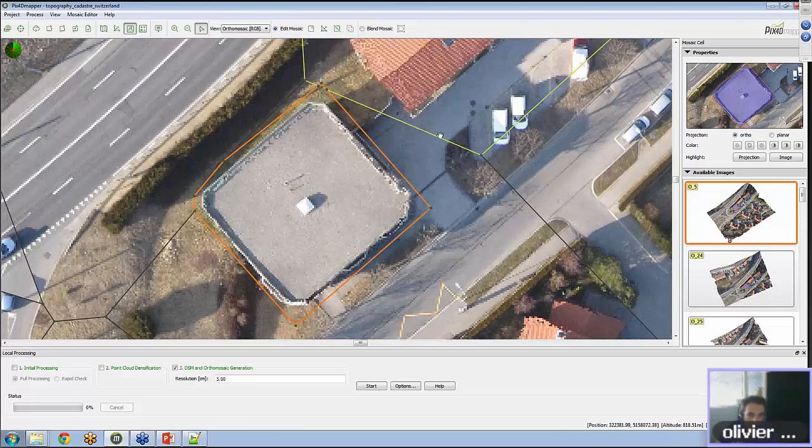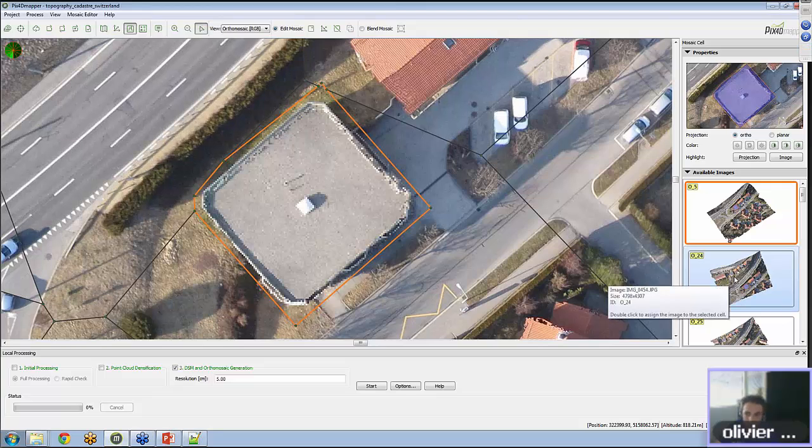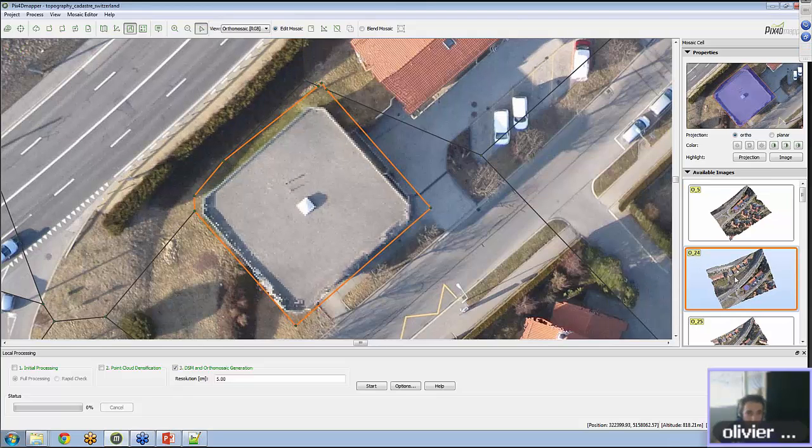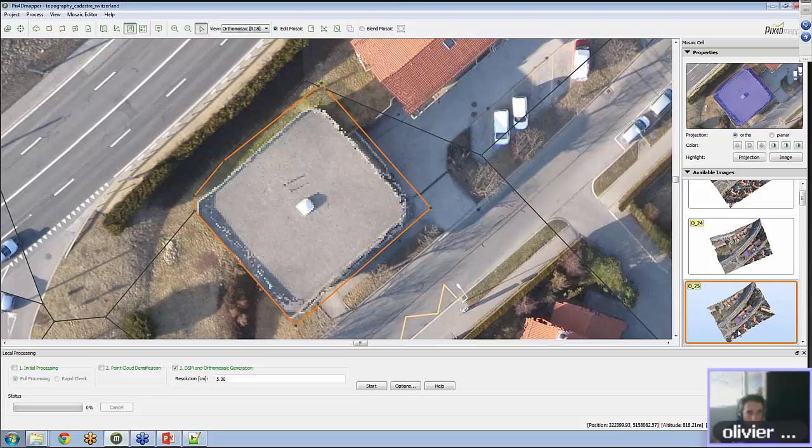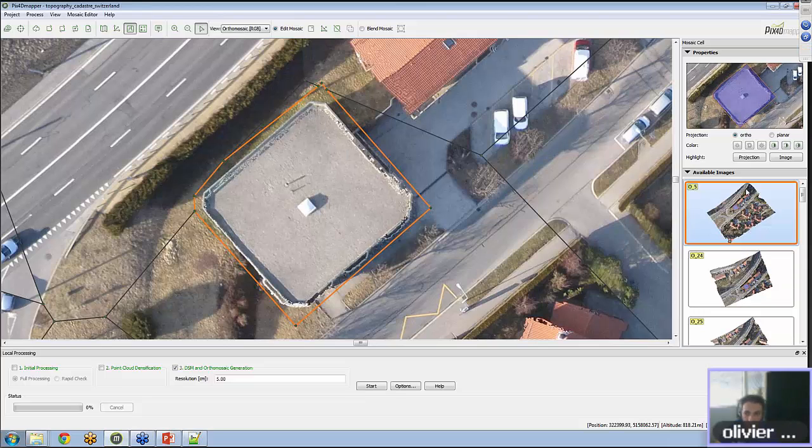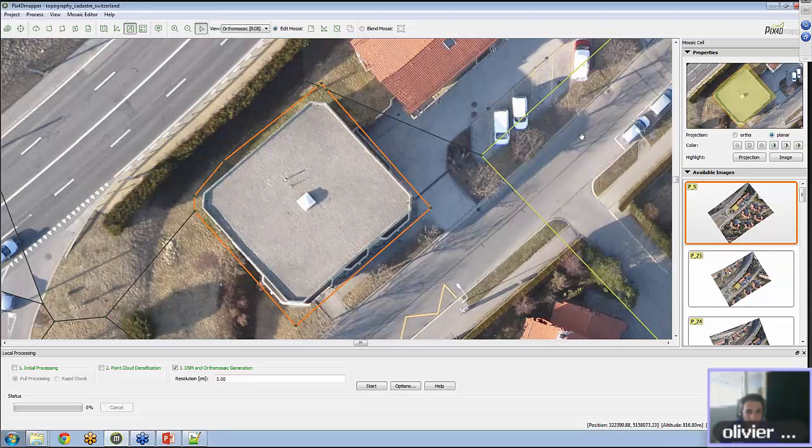So we start with the ortho and we see the distortion. How can we correct it? Sometimes another ortho projection is good enough and does not create artifacts, but with buildings, that will happen rarely. In general, with a building, we will need to go for a planar projection. In this case, the planar projection has more or less exactly the same scale that we have seen with the ortho projection.